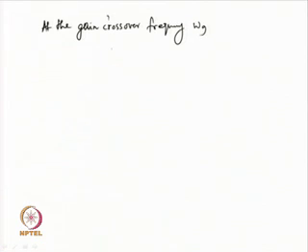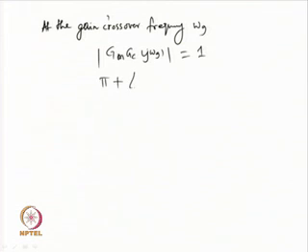So, the phase margin condition gives us that at the gain crossover frequency omega g, the magnitude of Gm Gc j omega g becomes 1 and pi plus the angle of Gm Gc j omega g will be equal to phi m, where phi m is the phase margin.